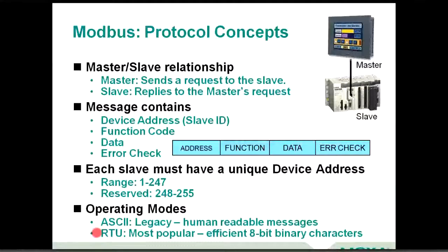Okay, so key concepts here: master-slave orientation, as we have with the HMI and the PLC in this. We have certain things that are exchanged. Each slave device has an ID, and most often folks are using Modbus RTU for what they're doing with that.